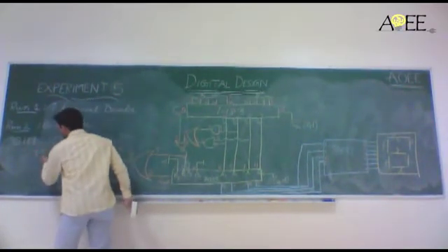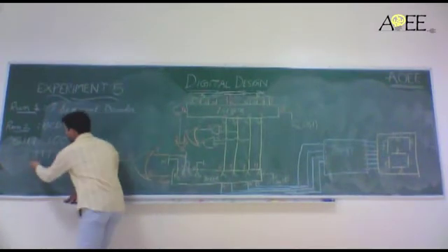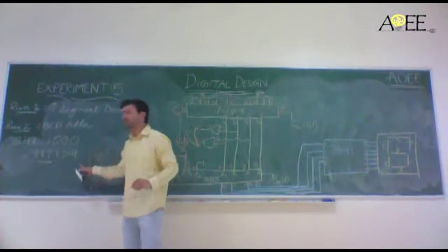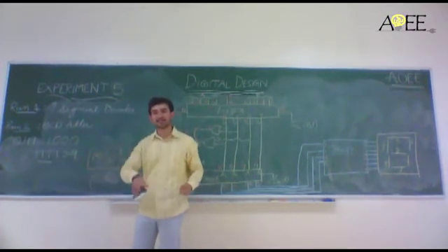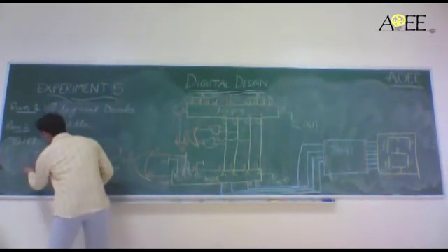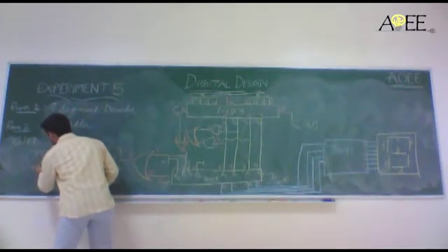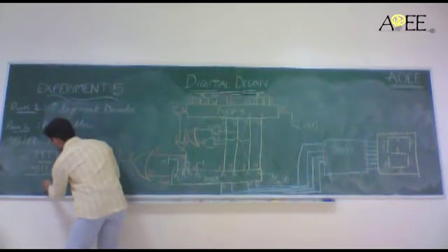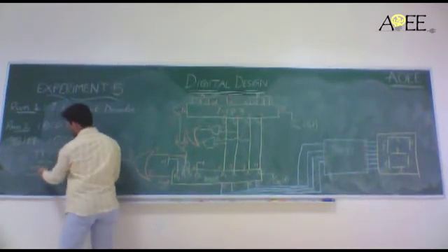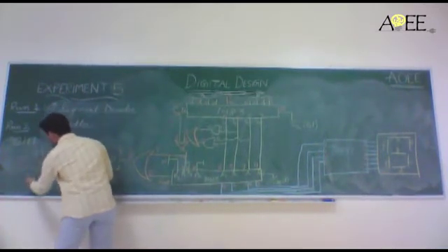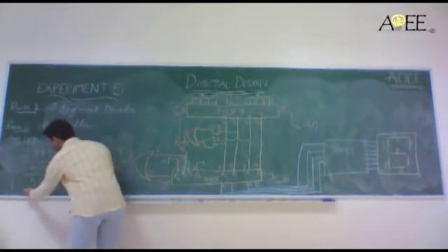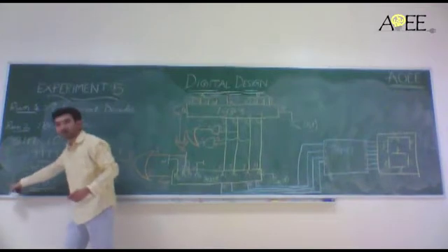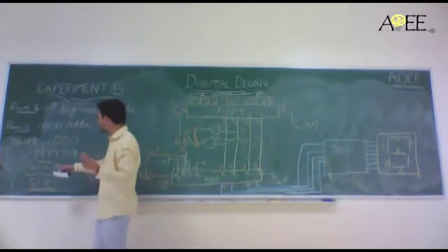15 is 4 times 1, triple 4 times 1. This number is greater than 9. Once any number is greater than 9, then 6 is added to it. If we add 6, that is, we add 0110. 0, 1, 1, 0 will give me 1, 0, carry 1, 1, 0, 1, carry 1, 0, carry 1. So, finally, I am left with 5 and 1 as an additional carry.